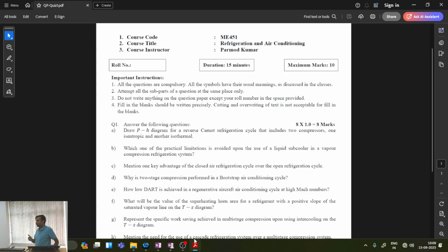If saturated liquid comes out of the flash chamber, there will be chances that before the inlet to the expander, a small amount of vapor forms. However, the expansion device is designed only for pure liquid operation. If some amount of vapor goes in, it will lead to sluggish operation, or there will be malfunction and the flow can completely stop. So to ensure that there is no vapor formation at the entry of the expansion device, we do significant subcooling. Okay, is this one clear?